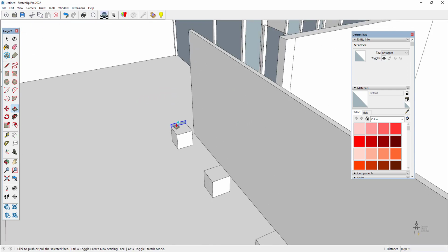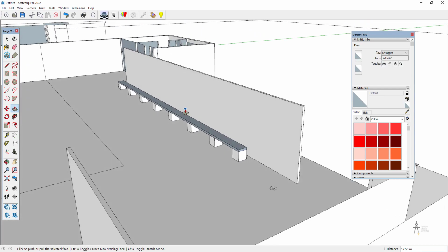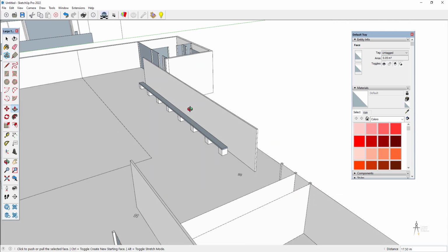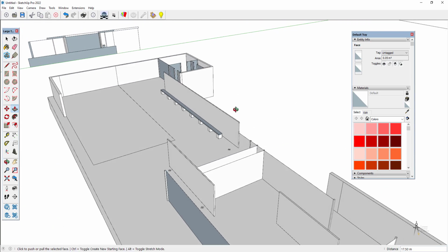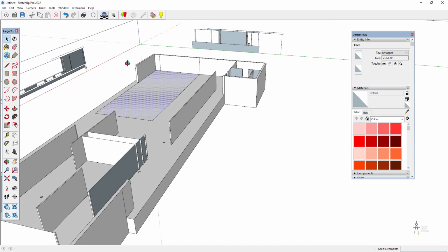I copy it here, and what I'm going to do is use the Push-Pull tool, and I'm just going to take it to the very edge of the last one of these cubes that supports the board. Excellent. This is quite a quick way. You could have done your own rectangle and then extruded it using another reference point. Anyway, there's several ways of doing it.